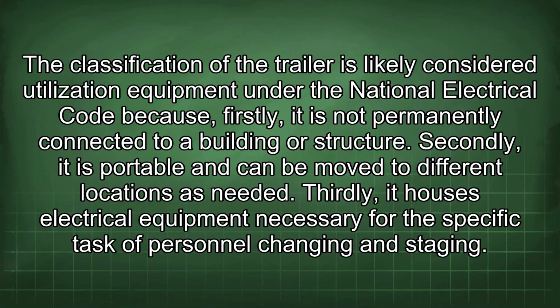Classification of the trailer is likely considered utilization equipment under the National Electrical Code because, firstly, it is not permanently connected to a building or structure. Secondly, it is portable and can be moved to different locations as needed. Thirdly, it houses electrical equipment necessary for the specific task of personnel changing and staging.